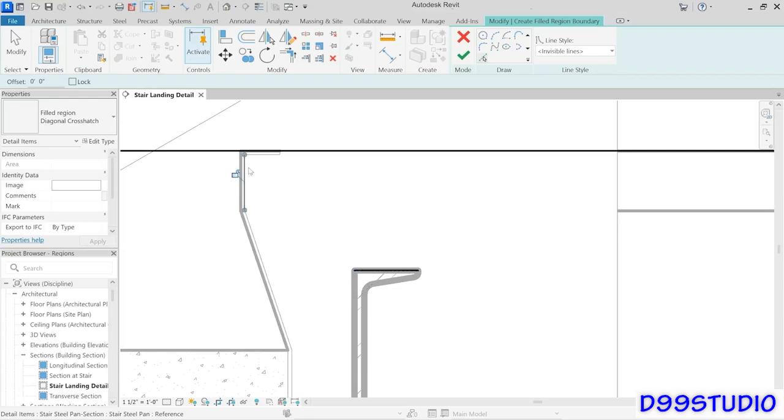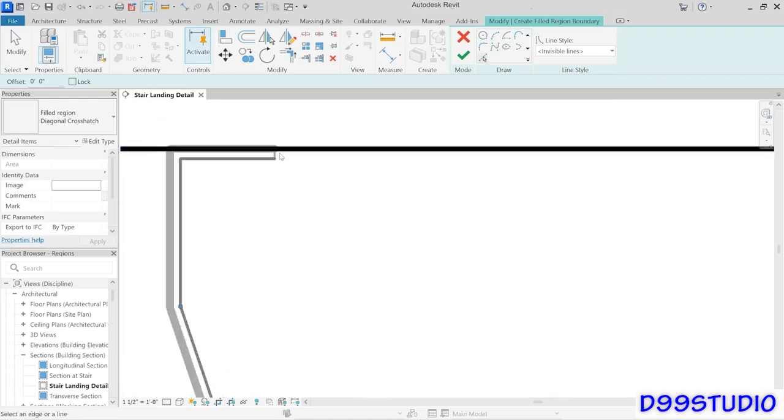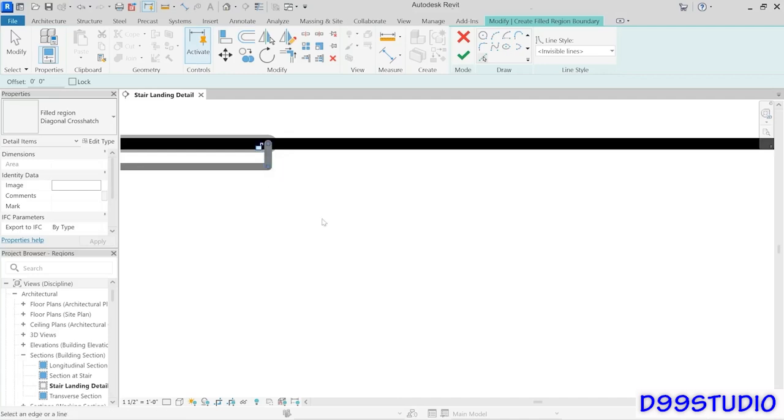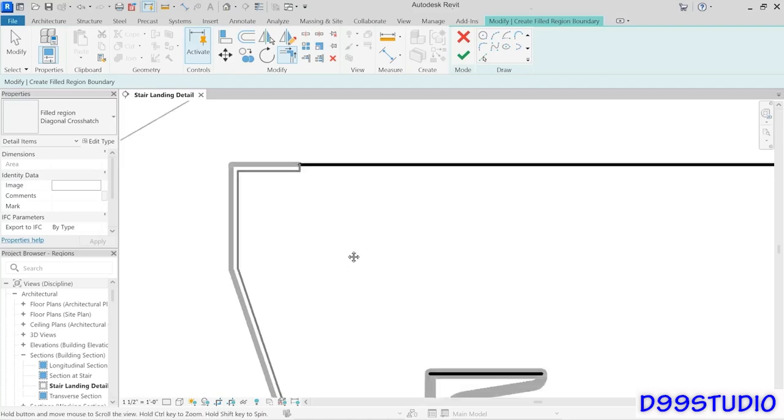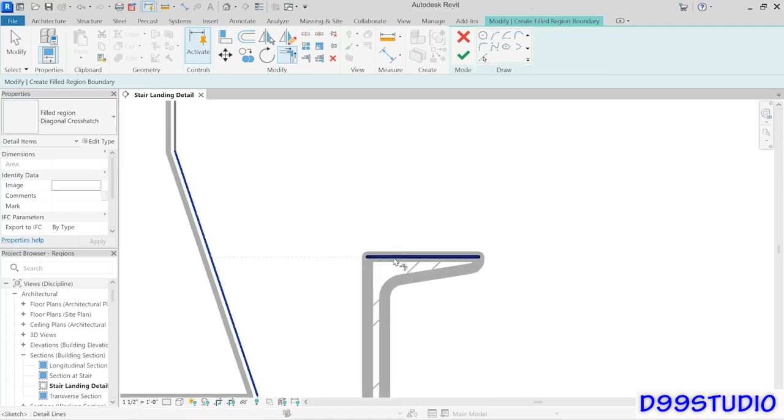So I'm actually going to use invisible lines to grab that shape. And then you've got to zoom in nice and close and get this little vertical line right there too. Remember, you have to have an enclosed sketch. So now I'm going to do Trim and Extend to a Corner and trim this item back to that little vertical line and trim this diagonal line to this one.